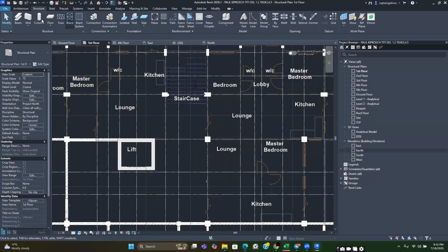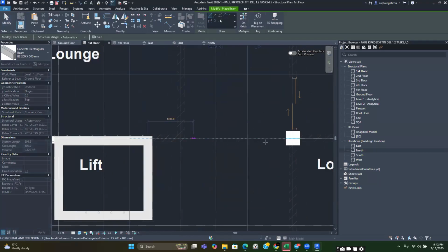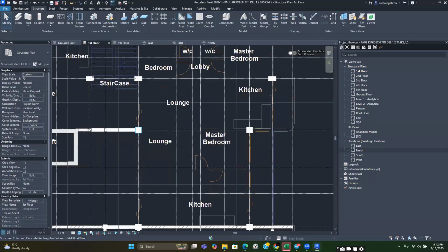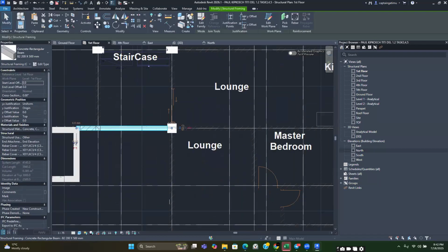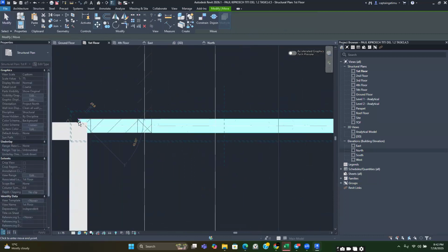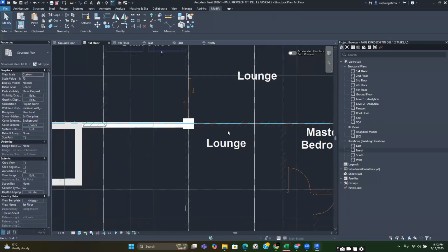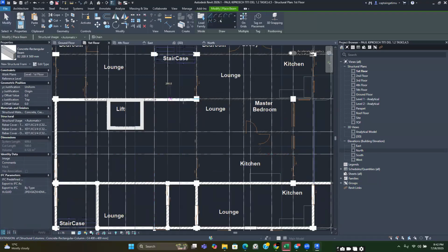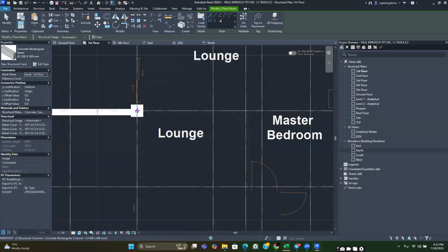So we go to structure, beam, and continue with the section that we have been using. We are going to move this one again. You can choose to move the shear wall or the beam, but since this is a training exercise, you can just move the beam to make your life a bit easier.